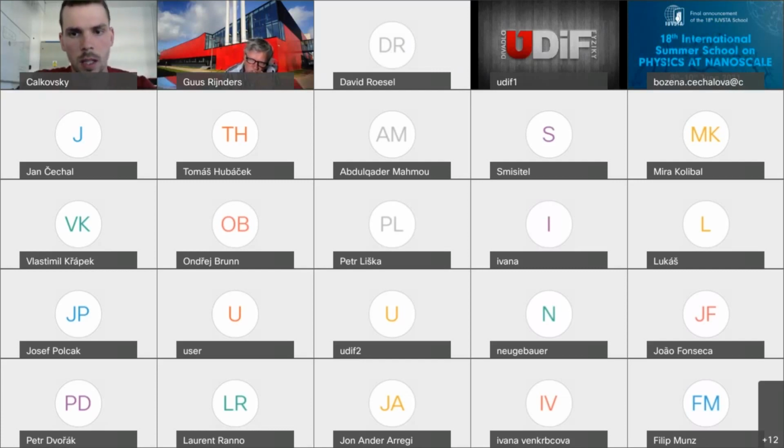Nice. Okay, thank you. There are actually a lot of questions, but we probably won't go through all of them. How did you identify MgO as a buffer layer for achieving PZT epitaxy on the gallium nitride? That's very good. Actually, this was not our work; I think this was work done at Penn State. They used sputter deposition on the gallium nitride already, and they showed that you could do this MgO trick with MBE type of growth, and we made it work also with PLD. So MgO was not our first guess, but just a literature guess.